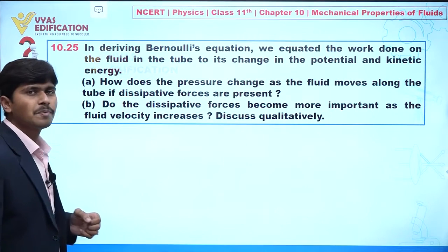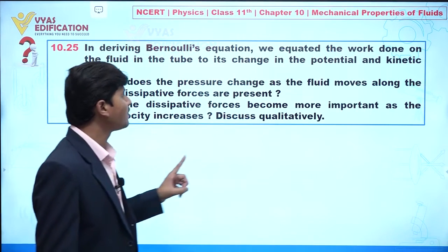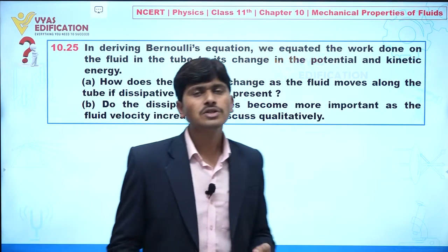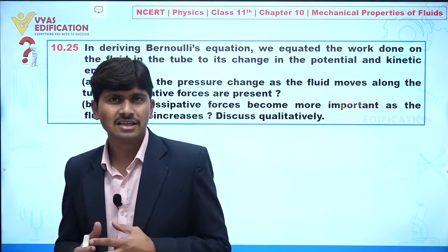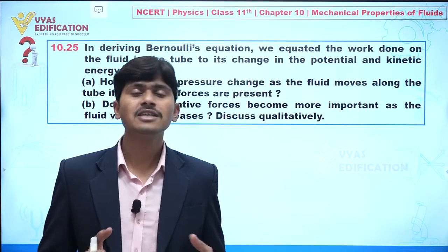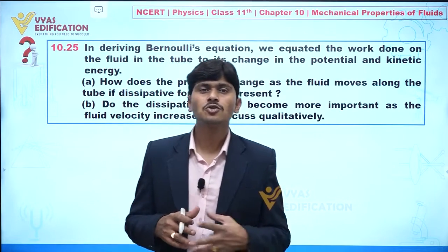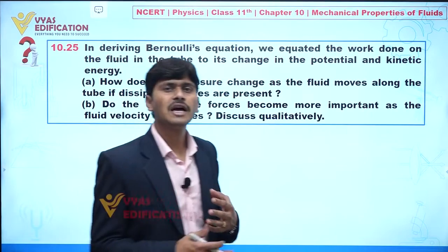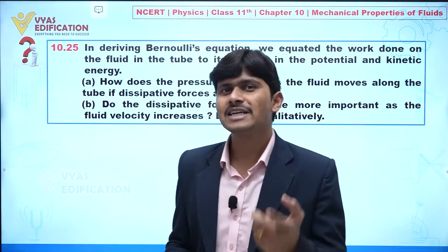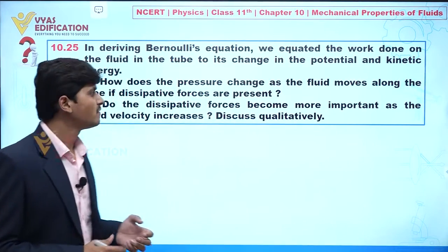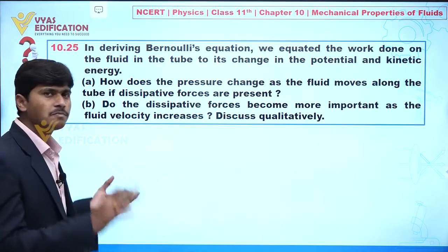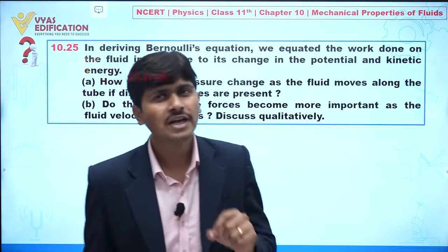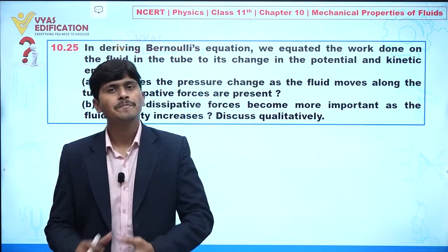Now if I am talking about part number B, do the dissipative forces become more important as fluid velocity increases? Yes, because as velocity increases, listen carefully, there is more tendency for the flow to become turbulent, clear? As well, the more velocity we have, definitely the viscous force acting will be more, clear? It means definitely we can say if velocity is more, dissipative forces will be more, and we will find more decrease in pressure energy, clear? So this is all about this question.